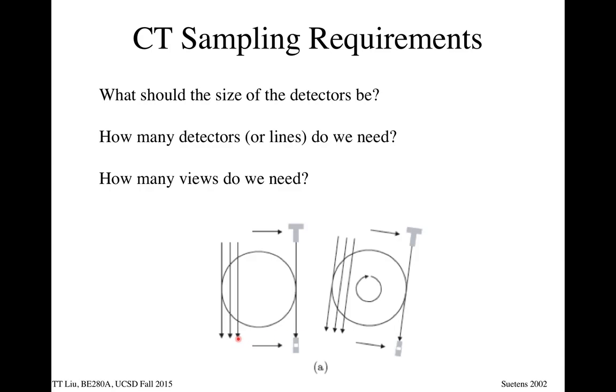So that's going to sort of set a sampling in this direction. And in the frequency domain, if I have that detector that's a rectangle like this, what do you think is happening over in the frequency domain? It's going to roll it off, right? Because as the rect gets wider, the Fourier transform of that thing gets narrower and narrower, so higher frequencies get attenuated.